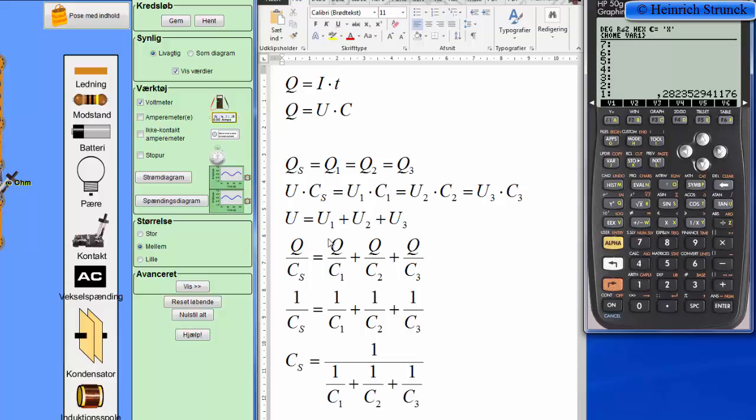So actually here the voltage across capacitor number 1 is the charge divided by the capacitance. So here's the charge, and then we can divide with the capacitance for number 1, 0.1. Then the voltage across the first capacitor should be 2.82 volt. Then we can do the same for the next one. And finally, number 3.